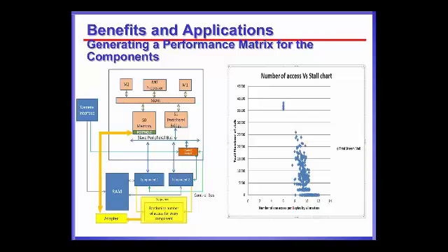So the basic bring-up tests that we created using this methodology were ported to the silicon also. Under the hood, those are just a few register accesses, and then we try to control some of the things from that. We configure the IPs and then trigger them through the processor. Once those IPs are triggered, everything remains as is in the system.